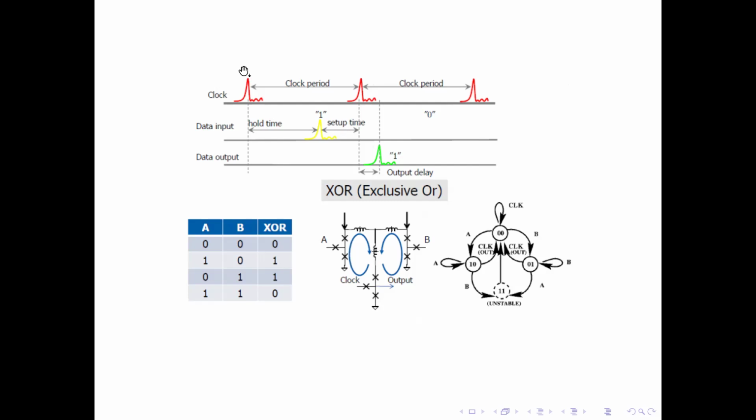So this is a very efficient representation of the circuits. And some people even expect that rapid single quantum flux electronics can replace semiconductor mainframe computers. Well, I would say the only problem is the lack of random access memory, because we have all the other circuits available and running.